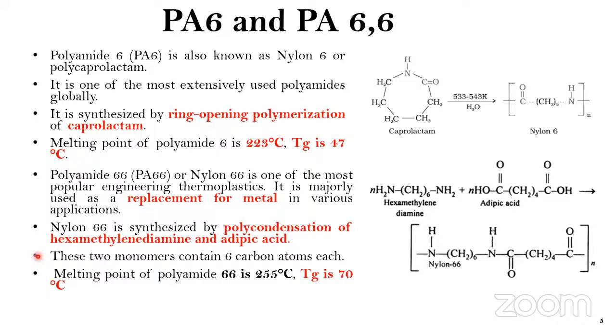Somehow that part particularly can affect the mechanical property of that material. So that is the reason we have to be cautious while using this material. We have to do the pre-dry, so all the moisture and everything will be removed and you can do your processing quite smoothly.